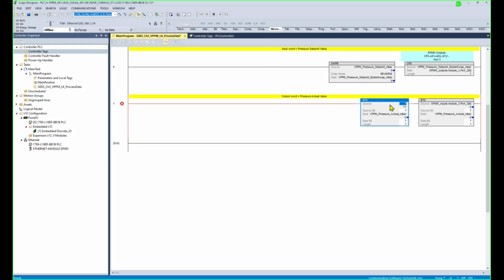Copy this on the left. Source bit is going to be 0 on both, and the destination bit is going to be 0, 8 bits long. This bit over here is going to be the higher bit, due to the swap. So we're basically swapping. We're going to put the low byte into the high byte area and the high byte into the low byte area.